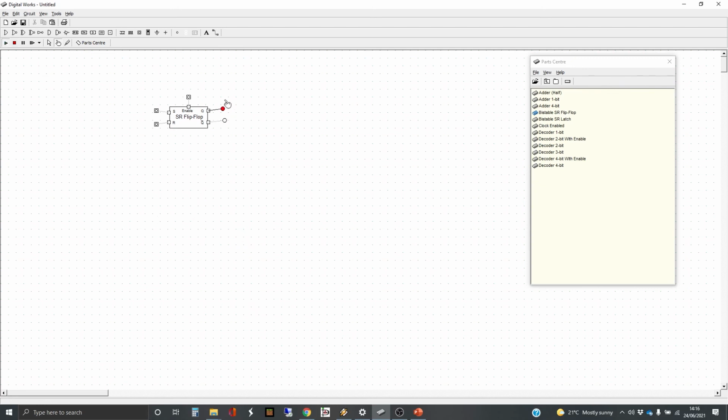So let's run, and immediately our Q goes high. We're going to do a reset operation, so let's set the reset flag and then give it an enable, and there we go. And we're going to test it again with it at reset, and there should be no change. That is correct. I'm going to change this back to S and enable. There we go. We're still in the situation where we've got both an S and an R, and if I set them both high and then do this, the two outputs become low, and then when we switch that enable off again, in electronics, this would be potentially random as to which one we get. Because this is simulated, it's more determinate, so we seem to be always getting a 0 at the Q when it resettles itself.